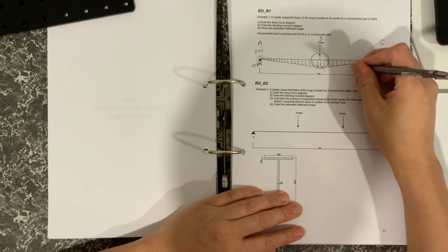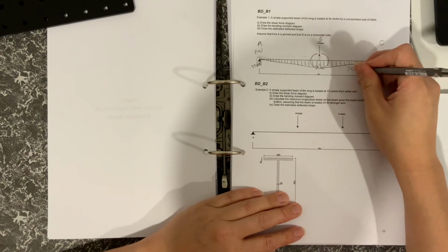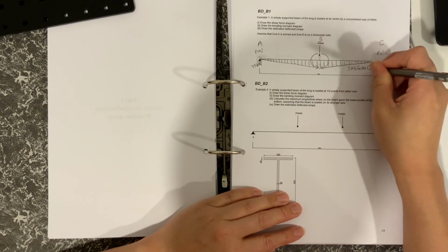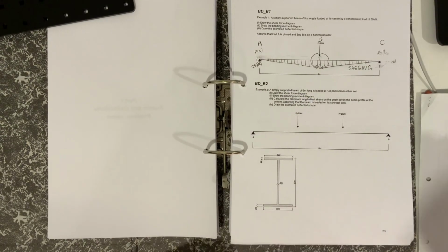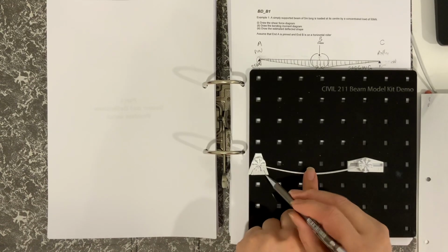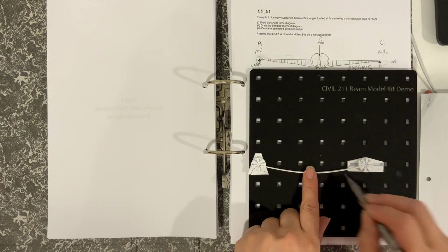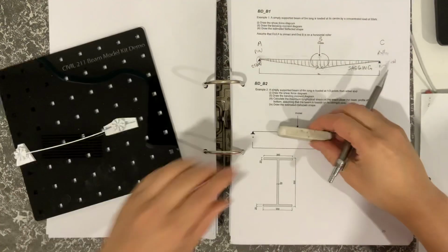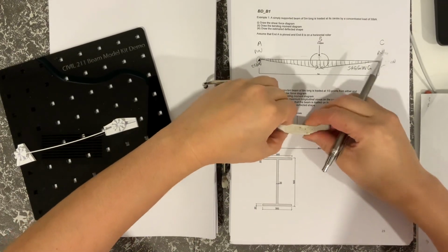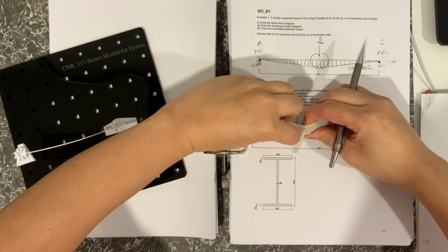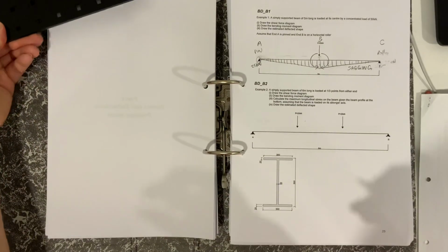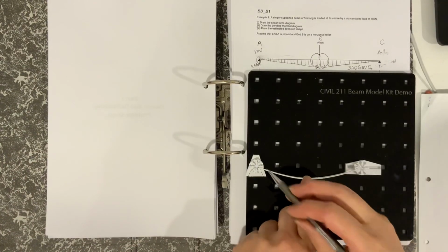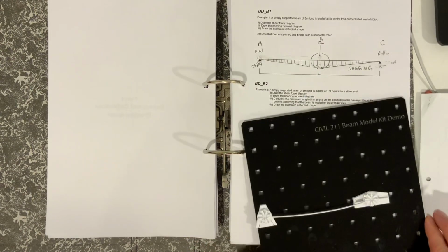So as we called it before, anything with the bending moment diagram below the line would be called sagging, and if the bending moment had been above the line, then it would be called hogging. Okay, and as we said, the bending moment is plotted on the tension side, so the bottom side, which you can see here. If you take this rubber and rotate it round there, that side would be in tension, so you're being consistent with plotting the bending moment diagram on the tension side.